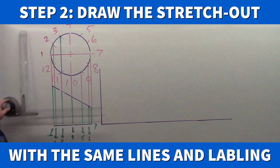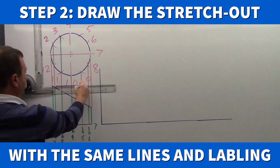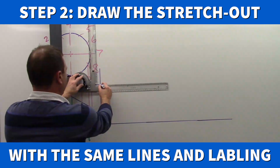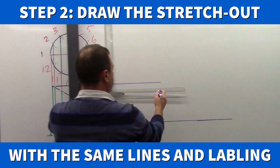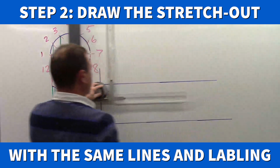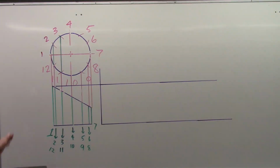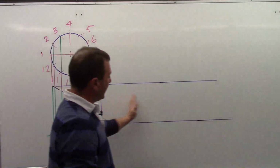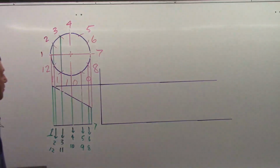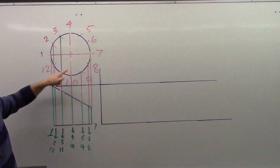For the vertical, though, I don't need to measure it. I can merely project this point straight across here to establish my height. So I project that one across. For the stretch out, or the distance this way, horizontally for our part, it comes to the shape we see here. Okay, the distance it takes to go around the part.